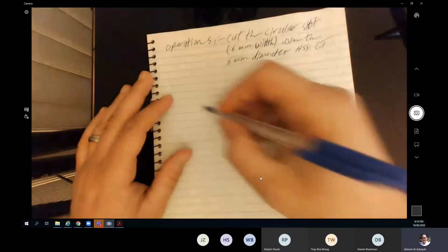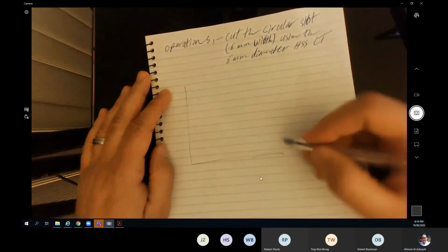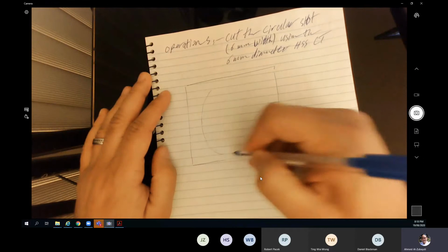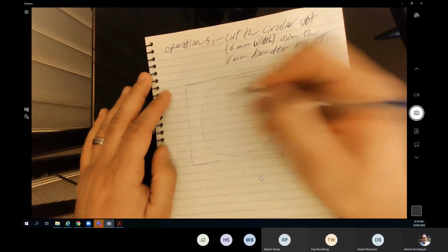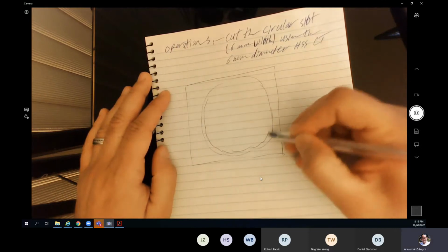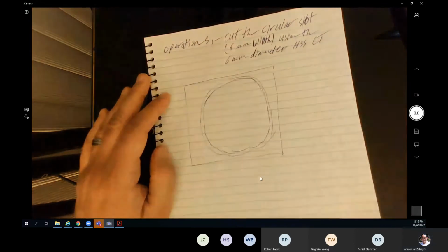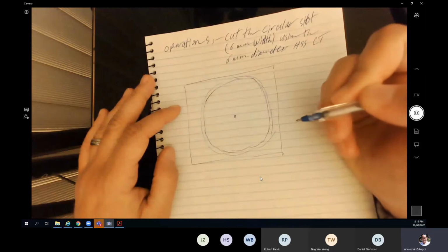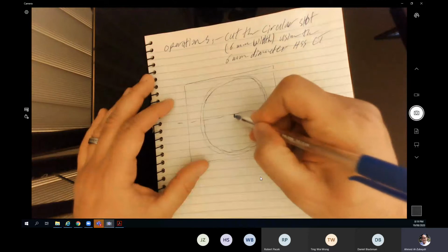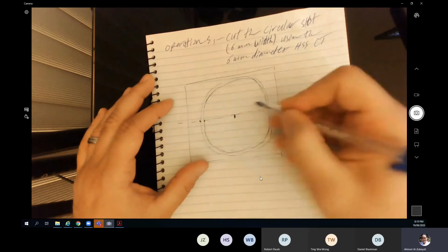Now this sketch is going to look like the following. Once again, we are not going to consider a lot. This will be the shape. Make a circle in the middle. Offset this circle by 6 millimeter to the inside. The outer one is 102 plus B. The inner one is 92 plus B. Okay, this is my center. Make a line here. Now, of course, I know the distance from here to here, and I know the distance from here to here, which is the radius of the two circles.